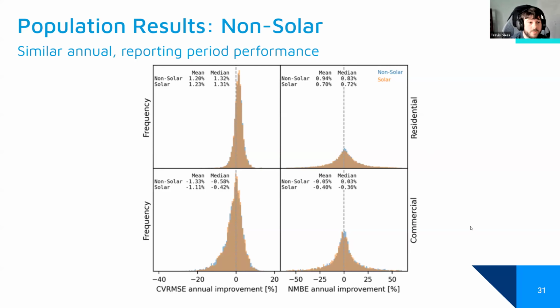That's a lot of detail to go into for a rather simple set of data. Basically, we see a 1.23 increase, it is better, for the residential CVRMSE, 1% worse. If this were me, if the model is 1% different and it's back and forth like this, I say it's a wash.